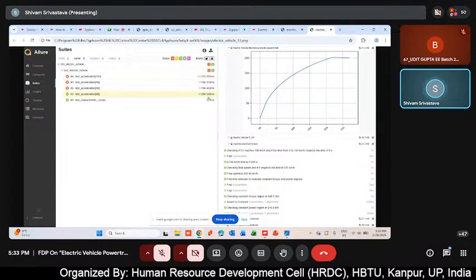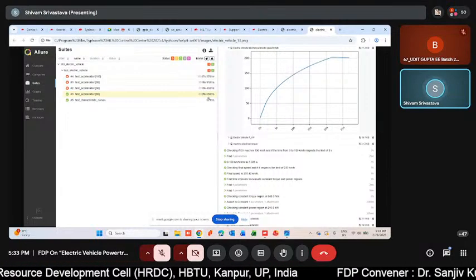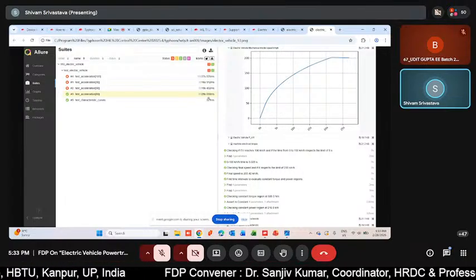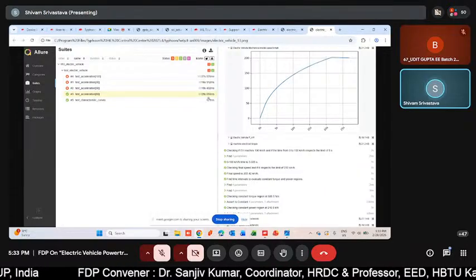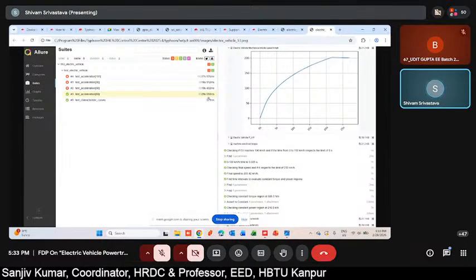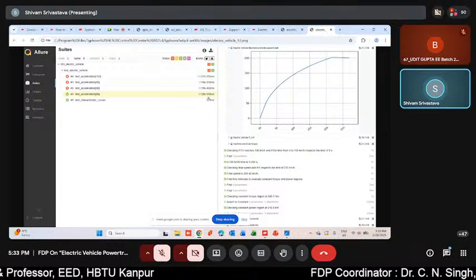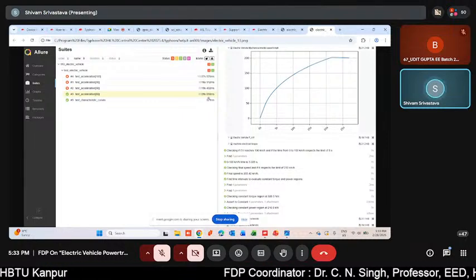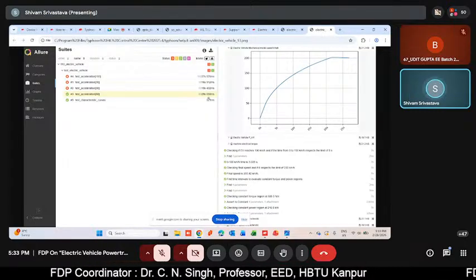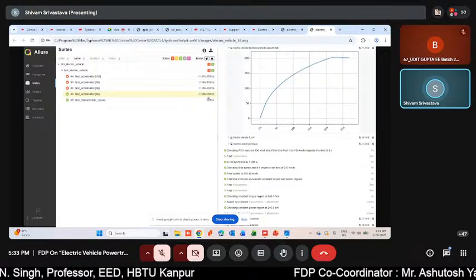So the test scenarios in the Typhoon Test IDE should be in the Python environment, so that if the user is not very confident with Python scripting, they can also take help from the API that has been created by the Typhoon team. Inside the APIs, they just need to give the name of the signal on which they want to perform the test, and the value at which they want to perform the test.